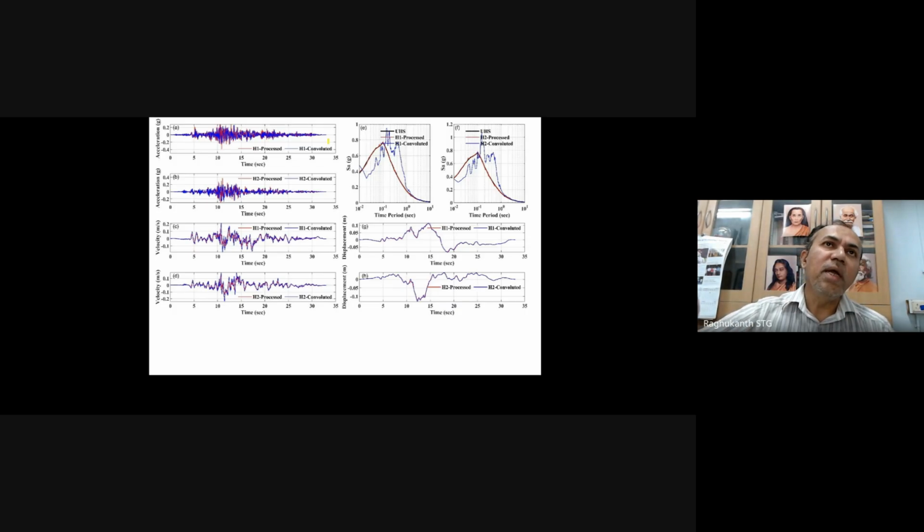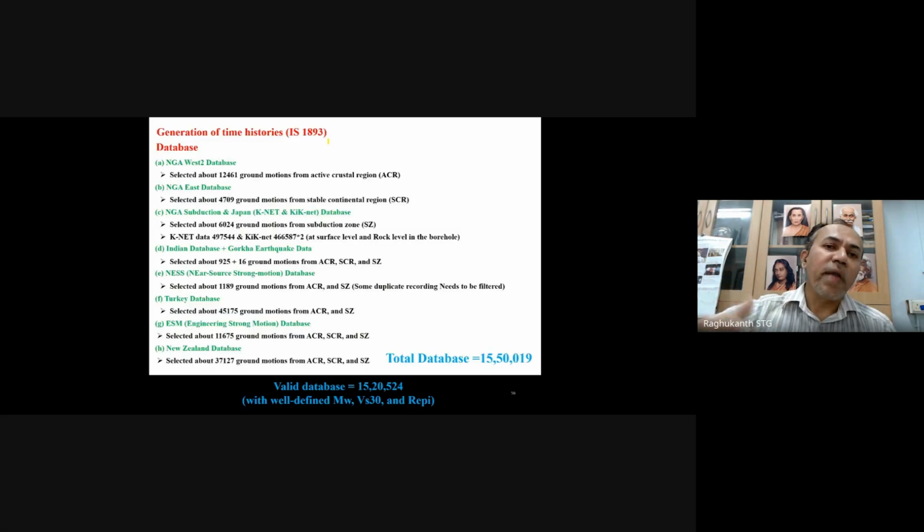We are going to post it. So these time histories are spectrum compatible with UHRS, that is Uniform Hazard Response Spectra. Now in IS code, what we did was, if they are spectrum compatible with UHRS, then that is fine for important structures. But if you want to do it for ordinary buildings, then how do we proceed with the time history analysis? Generally, the important structure is fine, but for common buildings, people don't want the actual spectrum compatible. They want scaling of time histories.